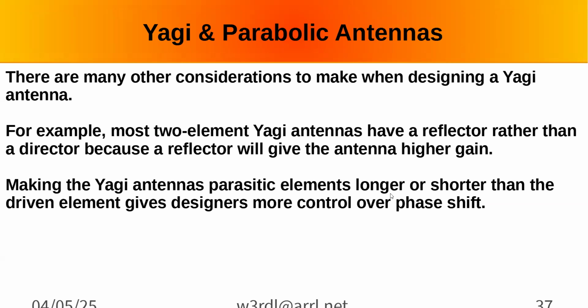Let's see. Yeah, two element Yagi, normally you're going to have a reflector and the driven element because you get higher gain. I'm not sure what the effect is if you just have a director.